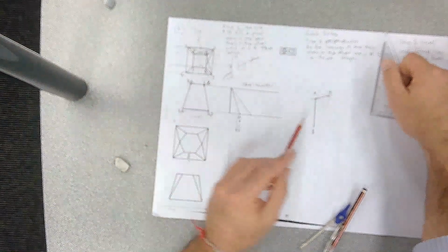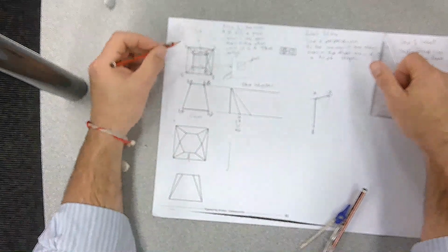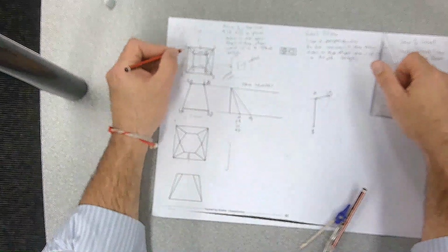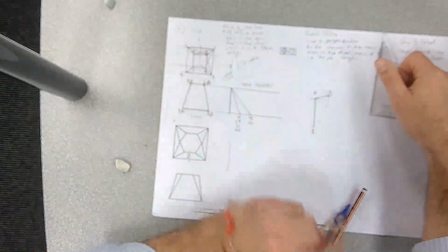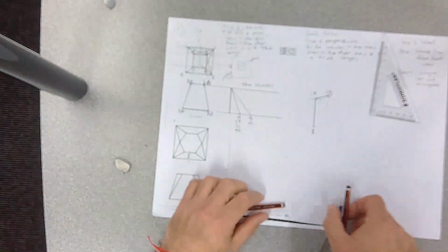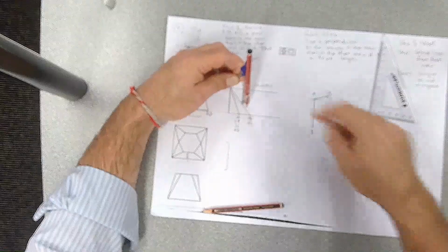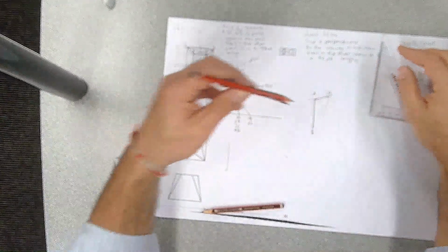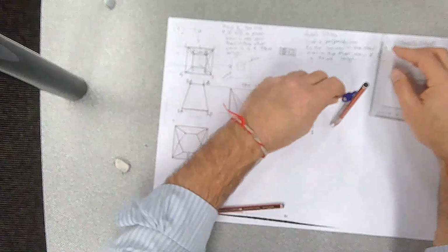Okay, so all of these lines, these triangle lines, the first one we did was 1B, but 1B is going to be the same as A2, etc., etc. All of those triangular lines, the triangulation lines, are going to be the same length. So we can now take our true length of A2 off our true lengths graph, because any line that's inclined is not going to be a true length if you take it off the diagram.